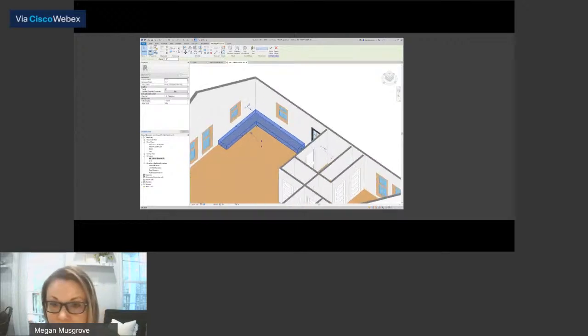So we're going to click on that, and right now this says extrusion start. It tells us where our work plane is. That's the first floor. We haven't done a whole lot and it wants to default to that. Later on, you might want to click something to change that, or you can pick your work plane, and we'll get to that later.